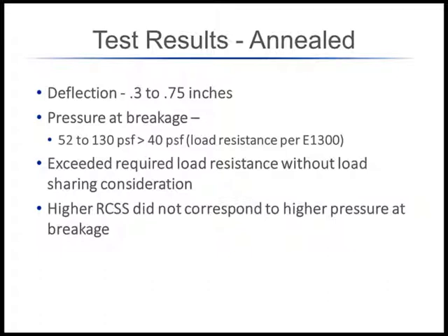Here in the testing that we did, we were testing the lights separately. So even on its own, the annealed lights exceeded the load resistance that you calculate per E1300. And another interesting thing that we found is that the higher RCSS didn't necessarily correspond to higher pressure at breakage.